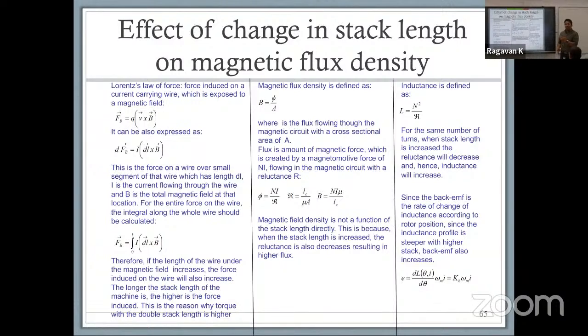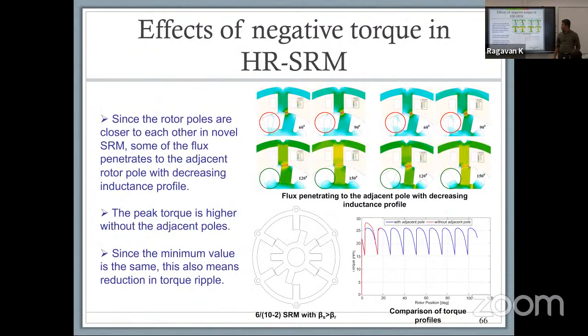So these are equations we are very familiar with. Based on that, you can define specific geometrical constraints that will allow you to decide what your back EMF on your machine is going to be. Why is this important? This goes now to the inverter. You have to know what the battery capacity of your system is, what the DC link voltage is going to be, and correspondingly, how many turns can you give? Because this E, while it tells you K times omega M times I, it also will be broken down in terms of N times I. How many amps versus how many turns, right? You're talking about H. H basically is N times I.